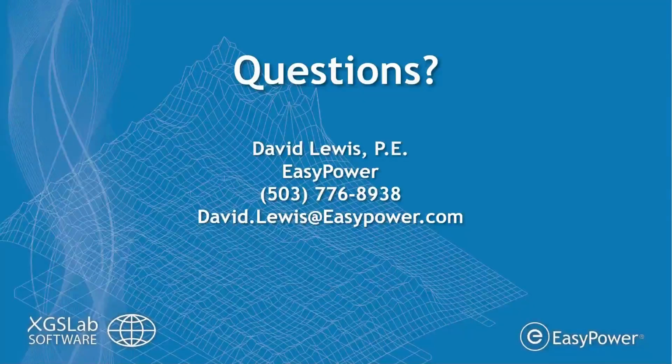In that particular example, it's going to give you worse results than you would really see in the real world. It's also possible, though, that the equipotential plane plays out in your favor in the grounding design, and you come up with a design that does not actually mitigate your transfer voltage concerns in the real world because of that assumption. So it's just something to note if you're evaluating software or doing hand calculations. I think I addressed most of the questions that came up.